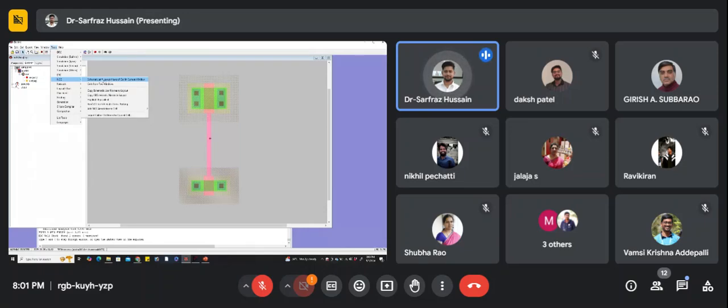Once this is done, most of our part is done. LVS we have done, ERC we did, layout versus schematic also done. Then next, you can also do floor plan and place. Current cell means whatever schematic you have generated, we can generate this directly also. We can go for the floor planning and placing also. Then there is this routing also.